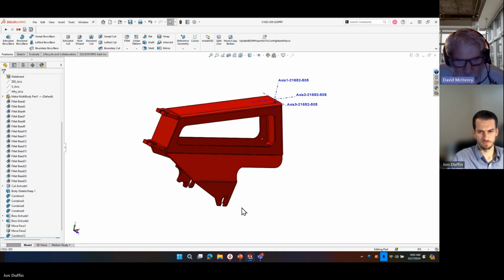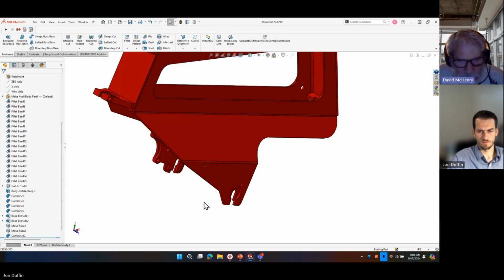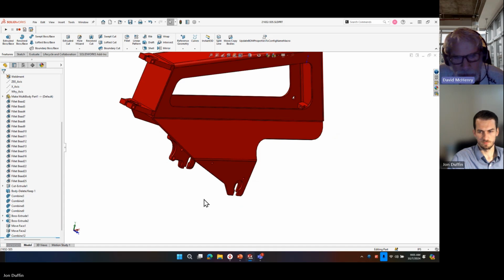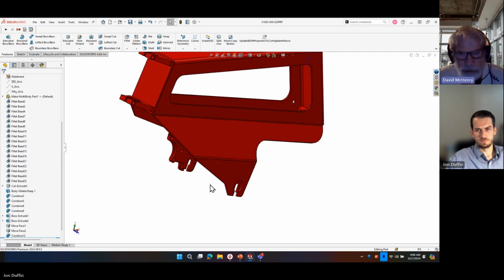We don't have to make a beam to go across these, because we could define this radius, this face here, and these pin holes as fixed and define this as a load, because that's really all that's going on when the rider sits down or is loading this point here. It looks ready to try to use Simulation Express on it.